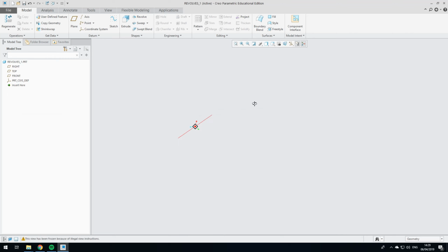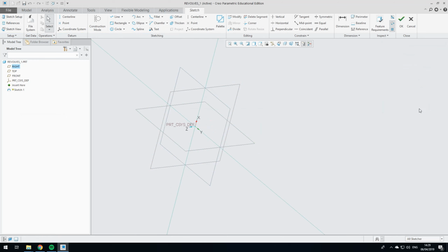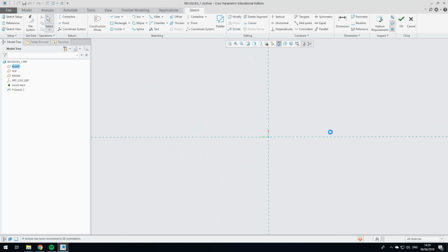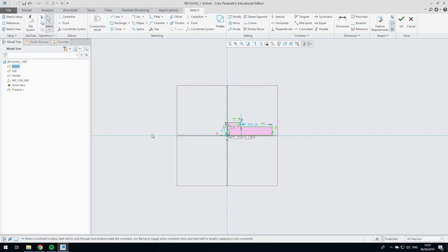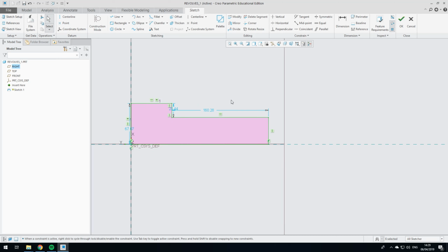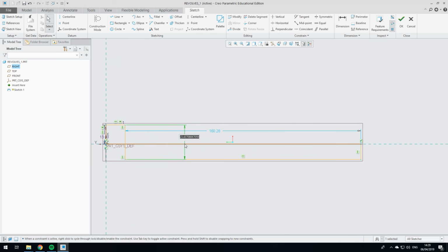Now we're going to do something ever so slightly more complicated, but still fairly simple. We are going to sketch a bolt. I'm going to do a cap head because it's the easiest to do completely as a revolve. So again, I've started sketching on a plane, and we draw the basic outline of the bolt, which we all know would look like this. Because you're doing a revolve, it's very easy just to draw the profile like that. If you did a cross section of it, what would that cross section look like? And then we will add the dimensions in now. I'm doing these off the top of my head.